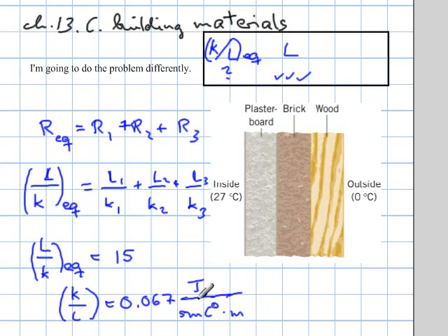So this first part here can be readily compared, and as I said, the conductivity went down, which makes sense because we're sandwiching these together in series. The heat resistance should move up. By the way, that 15 that I calculated a moment ago, the reciprocal, which actually is the resistance, could be kind of considered an R value.